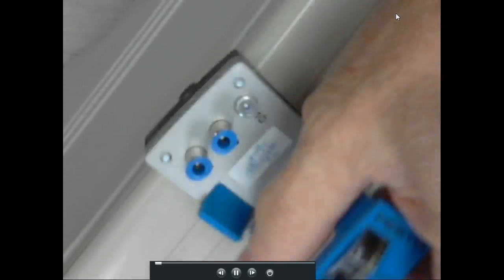You see right here is a little knob, and I'll pass this around. Here's a little adjustment where we can set the time. The time is in seconds, so this gives us an indicator of the time. And these are our two ports right here. Port 1 is the pressure port, and port 2 is the output. What you'll notice is when 1 goes true and we put pressure on it, there's going to be a wait before 2 actually outputs the pressure, which is pretty neat.